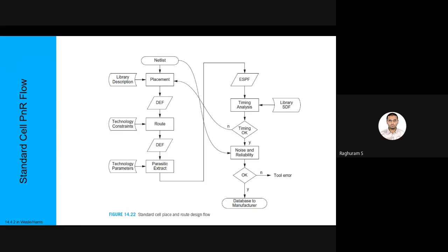Along with the interconnect, is the design still satisfying my 200 megahertz clock? Before, it was satisfying 200 megahertz because there was no resistance or capacitance concerned with the interconnect. But now since that information is there, we have to account for that also and still see if it is satisfying the clock, and if not, there is a problem.